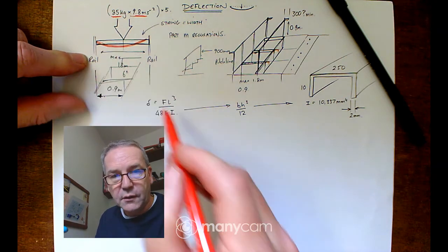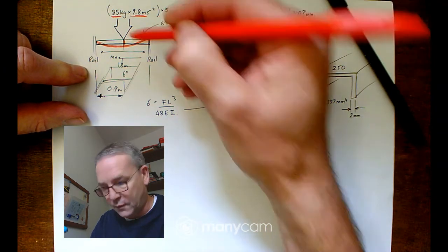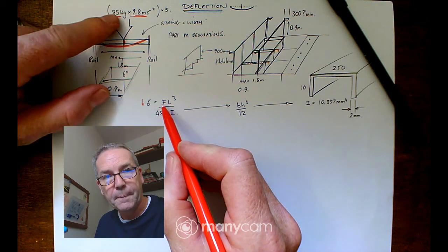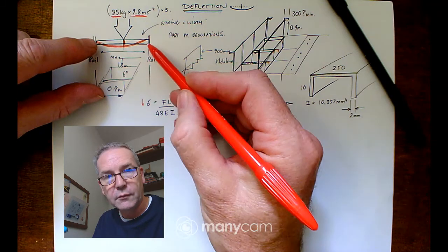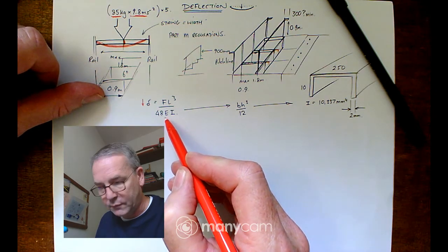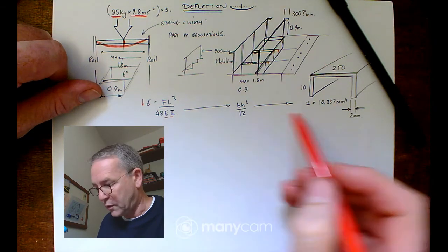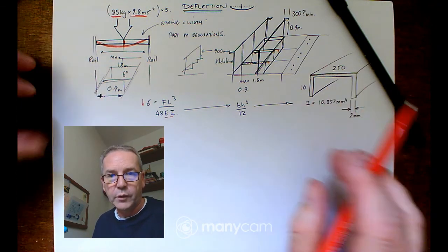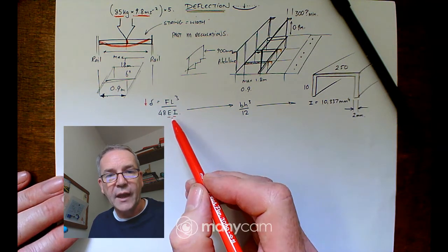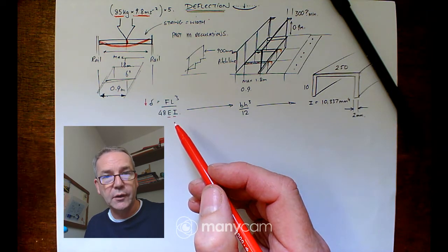And the idea is that there is an equation here that describes this deflection, which is the force being applied over a length, dependent on the material, the Young's modulus of elasticity, and the shape of that material from its inertia, which we've already calculated. Now we're going to take this step by step and redo this calculation, because this equation has to deal with everything in SI units, and as you know, SI units is meters, kilograms, seconds.